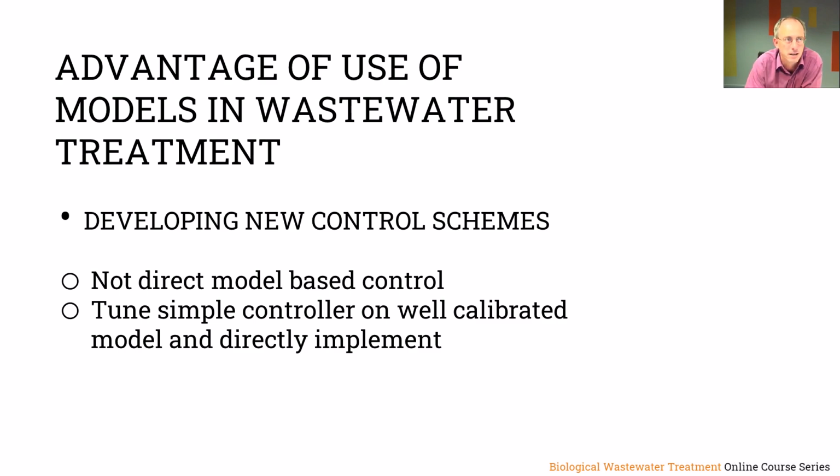So it's setting a PID controller, the set points, etc., and the regulation of the PID controller based on the model, and then transferring the controller directly into the controller at the treatment plant, and in this way having a much quicker introduction of a new control scheme at a treatment plant, where typically in the past the optimization of the controller would be done at the site, and that's of course much more difficult testing than on a model, because the treatment plant will have to keep working well.